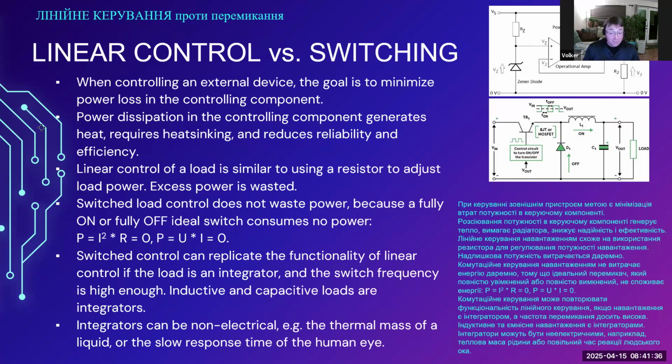Integrators can be non-electrical, like thermal mass, or also, for example, if you are using an LED. In most cases, LEDs are not voltage controlled. They are switch controlled. They are PWM controlled. And in this case, the integrator is the human eye.